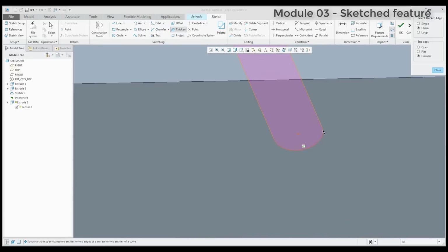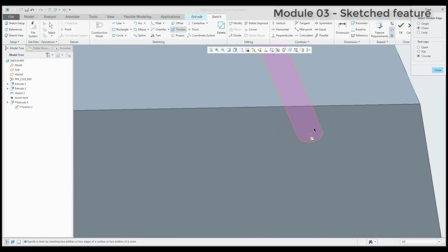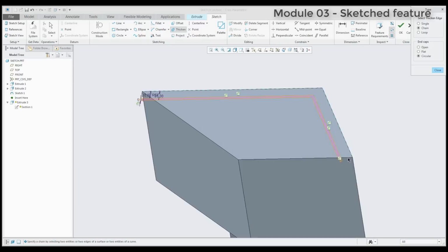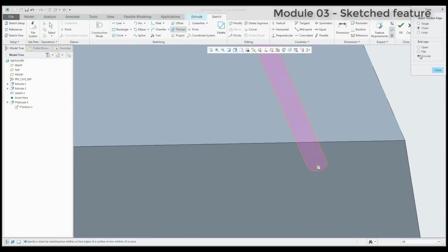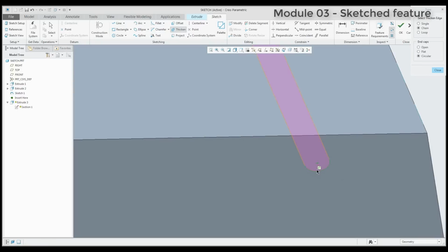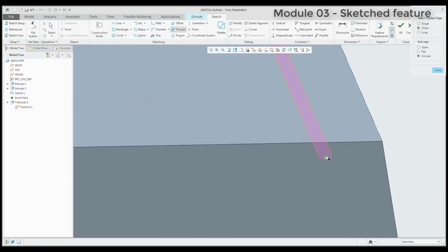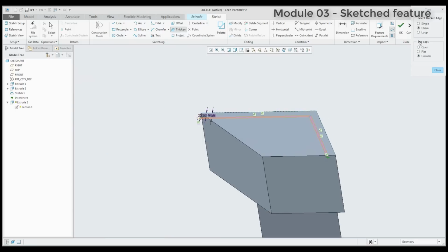So you can see here that my thickness is 5, I specified a 5, and the offset was defined by dimensions, offset dimensions. And open, flat and circular. Open means that you don't want to see that curve. If you specify flat, it will be a straight line, and if you use circular, here is the example. So if I would like to go the opposite way, I'd like to use the single, for example, open,